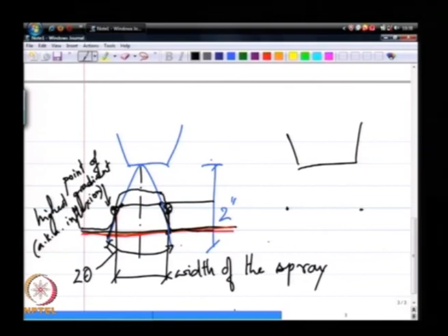But this is going to give you a higher source of error in comparison to making the measurements at two positions, primarily because most of the time the spray is sort of collapsing onto itself due to air entrainment, not due to gravity, due to air entrainment.